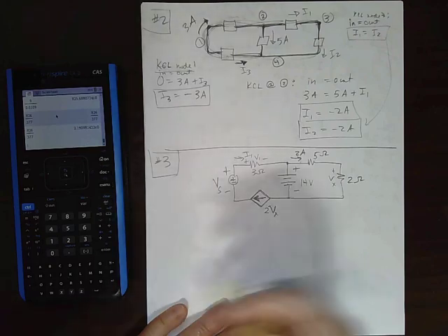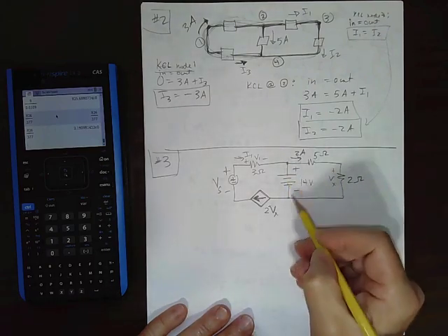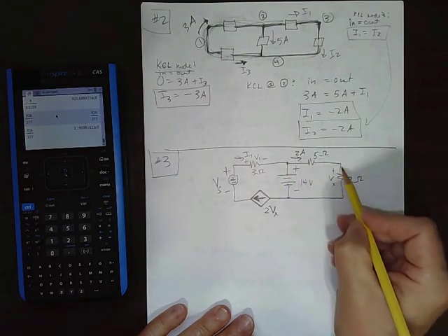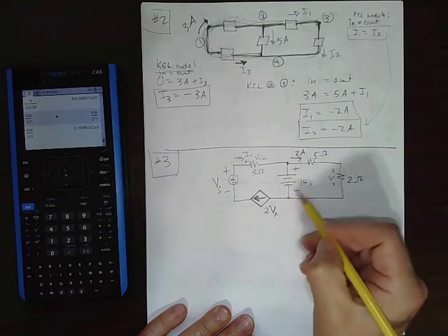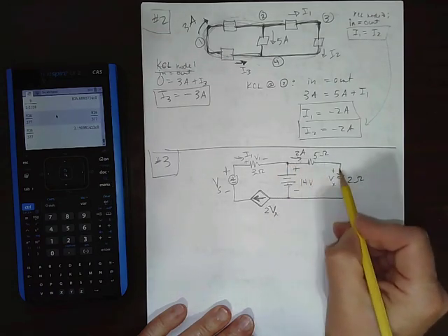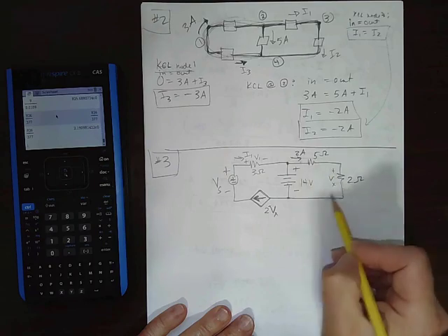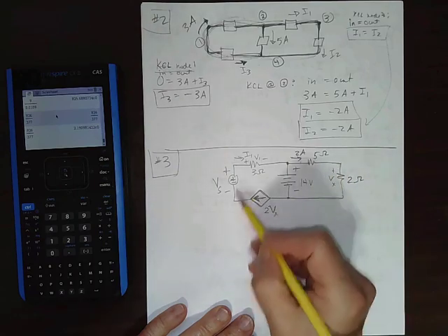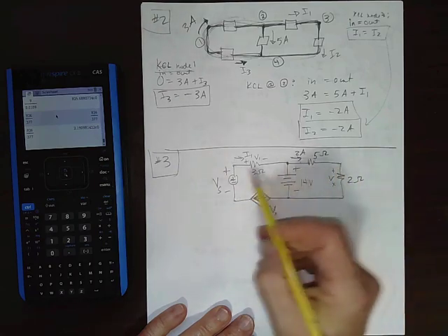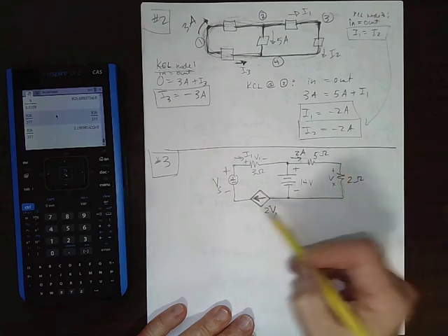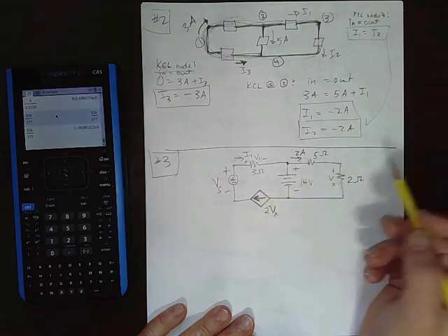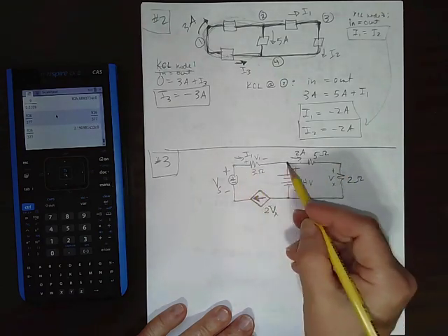we can get Vx, right? So again, let's identify our currents. Remember this 2 amps. Let's identify what's in parallel, what's in series. So this whole side, these two are in series, right? We have nodes here, here, and here, but most of these 3 nodes are boring nodes because they're only joining 2 elements, right? So this whole branch is in series.